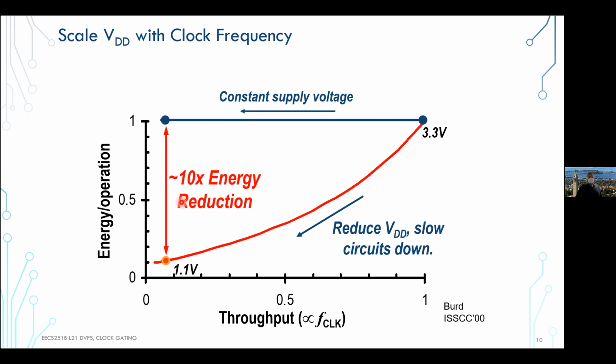And so how do we do this in a way that rides this curve? Because obviously, if I go around this curve, on one end, I'm not going to satisfy what the circuit can do. If I'm scaling the supply, I may be requiring my circuit to be at a certain voltage, produce a certain delay, but my throughput target is more aggressive. So then I'm not meeting it. So I need to ride this curve as tightly as possible.